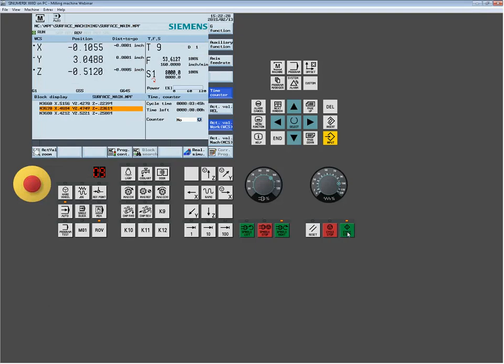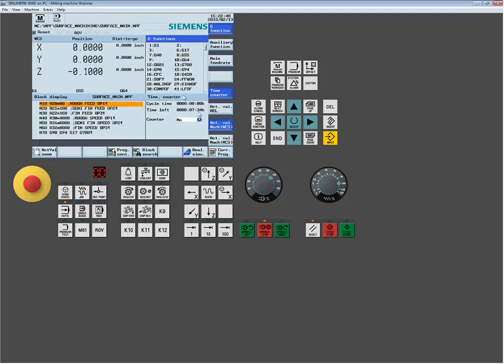We're going to put a real tight tolerance on it, really choke it, and you're going to see it's going to add quite a bit of cycle time. And if I bring up my auxiliary functions, we shaved 10 seconds off, nothing too dramatic. While I was running, I would have seen the done would have been at rough. So I was starting to see a little bit of a result change.